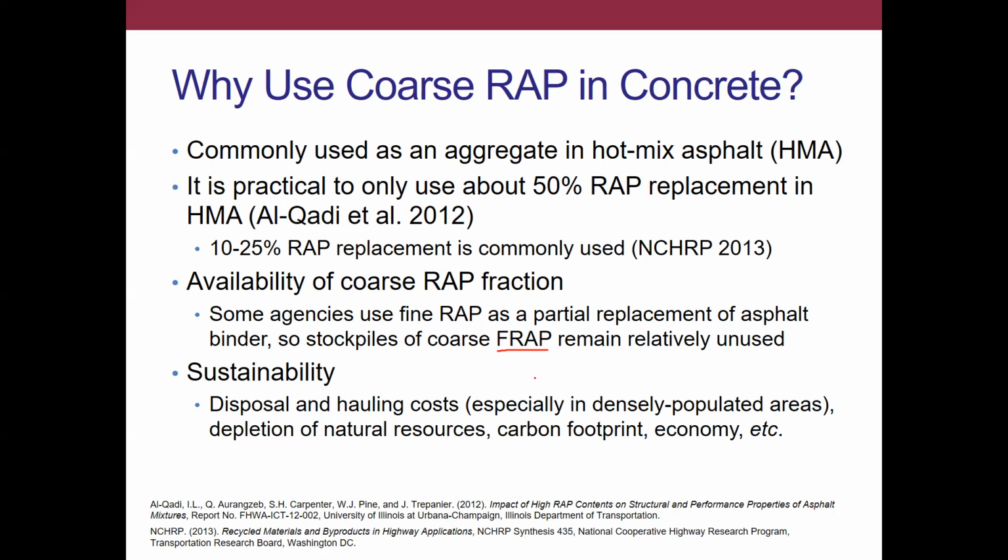But as you get closer to larger cities, particularly in my area, we're maybe about 4 hours away from Washington, D.C., as you near that region, they have significant issues with stockpiling this material. There's simply not enough land, or it is too costly to stockpile it. So of course, there's the sustainability question of finding alternative uses for this material. In addition, we can also consider options of partially replacing the virgin or natural aggregates in concretes as a sustainable option to use less natural resources.